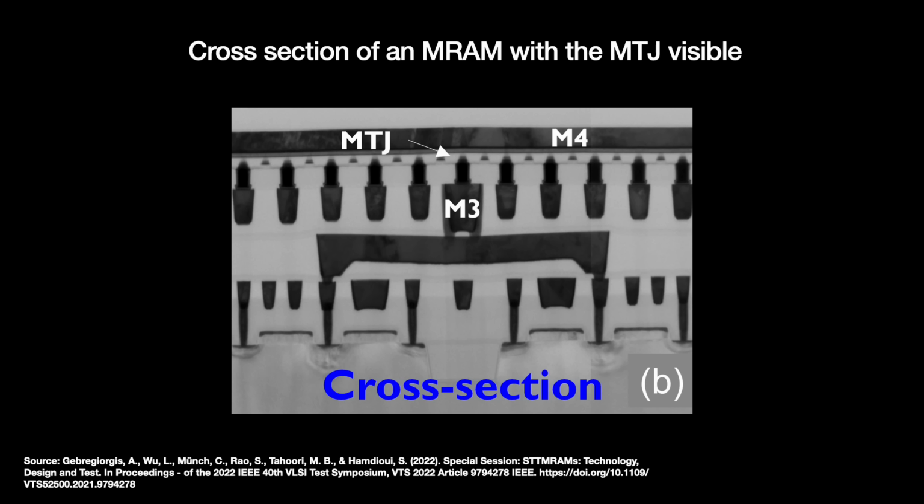At the 3 to 5 nanometer class nodes, the STT-MRAM gets so small that we need a decently strong current to properly write to it and avoid thermal-induced bit flips. But advanced node transistors are so small and delicate that such a current cannot be easily delivered.